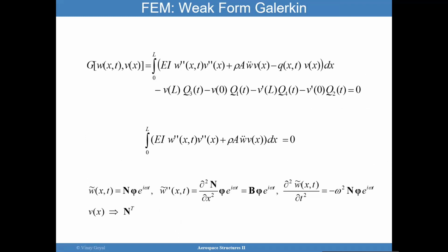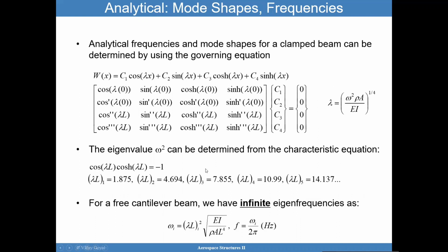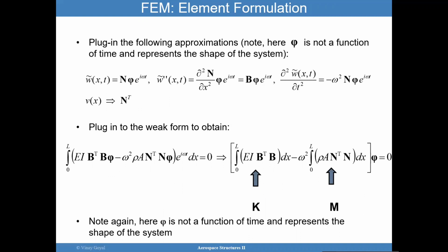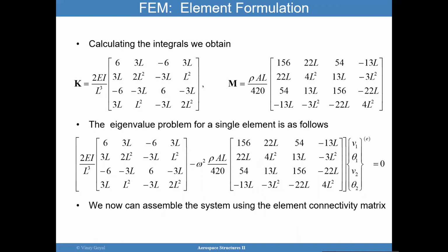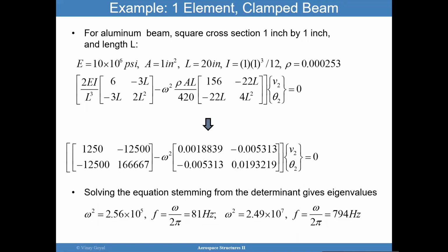I've taken this system right here, which we showed could have an infinite number of eigenvalues and mode shapes, by the way. And by discretizing it, and I don't want to go into the details on how the discretization works because that's what a finite elements course is about, I'm just giving you a top level view of what's going on. I've discretized it this way, and there's nothing more I can do. There's only two frequencies I can calculate because I've discretized the system.